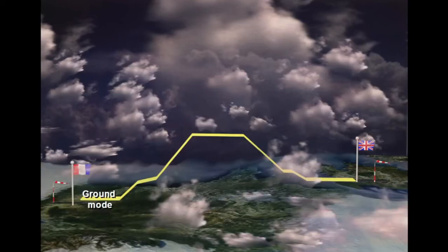Assuming the failure occurs while in flight. Pitch control retains load factor demand, the same as in normal law. Roll control reverts to direct. Surface deflection is now proportional to side stick deflection. Roll is more sensitive and aircraft reaction is proportional to airspeed. Yaw control: turn coordination is lost and only limited yaw damping is available.